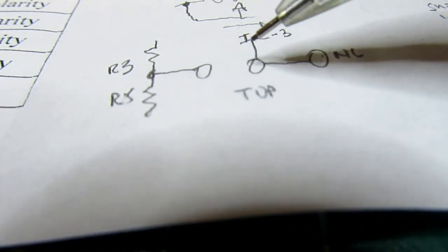So since it's reading the wrong way, what we really want to do is get this over to here and put the jumper here. You definitely need to move this jumper to this side. So you basically are going to have to cut this and cut this, then jumper this point around to here, and put a new jumper in here. Pain in the butt.